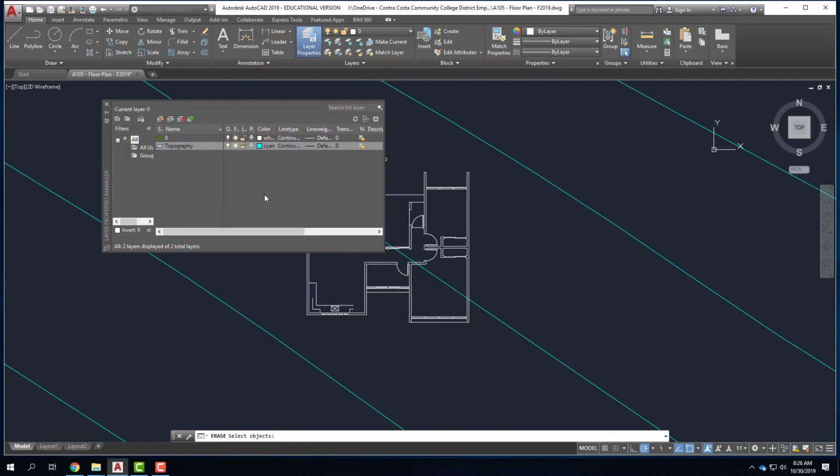So when it comes to actually creating your layers, you can create layers for whatever you want. You can name them whatever you want when it's your drawing. So right now you could create a layer for walls and you could just call it walls. If you go to work for a firm, there are standard layer names that typically a firm will have you adhere to. This improves consistency when you hand your drawing to somebody else and they hand it to somebody else. Furthermore, when you're working with consultants, an engineer, for example, a civil, mechanical, an electrical, whatever, they will also create layers on your drawing and they will name their layers accordingly. And so there's a way of kind of setting this up. The way that is typical, and again, it's going to depend on what firm you're working for, is that things that belong to the architects or things that are architecture related will be A_something.